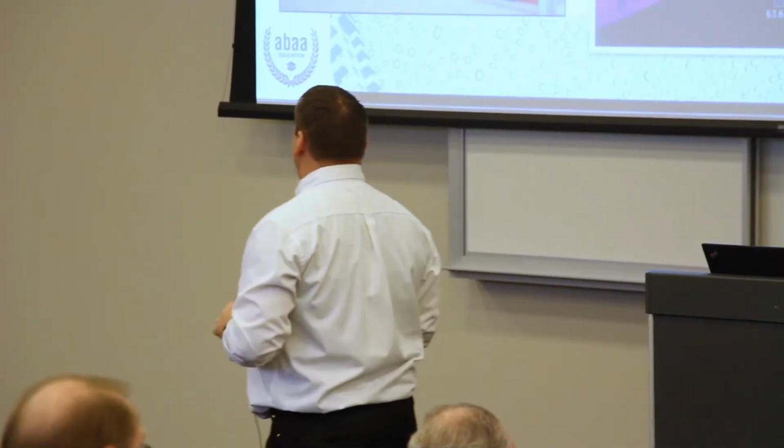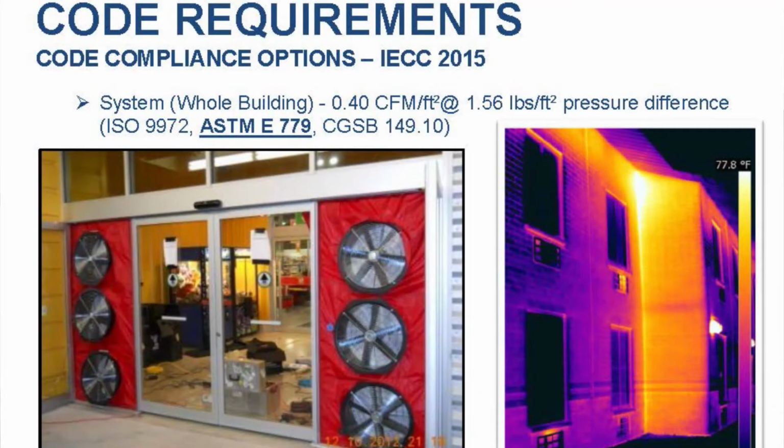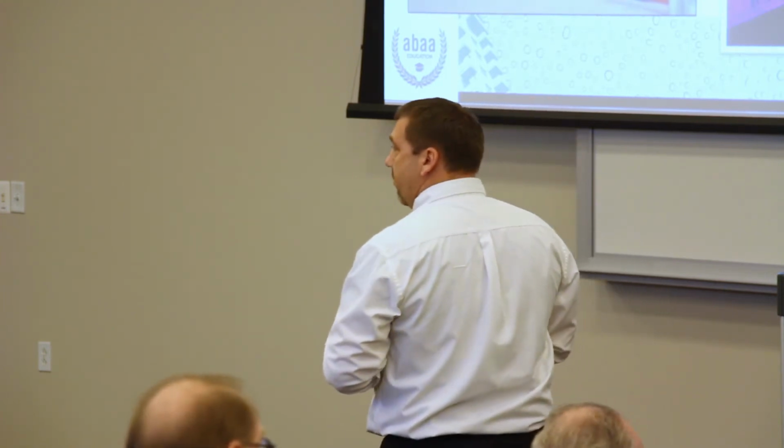We're going to talk about, again, whole building air tightness testing. These are getting easier and easier to run. They're using these small little fans they can place all over a larger building. They're doing multi-story buildings all the time now. Those fans get tied together, either Bluetooth or wireless or Cat5 to a computer, and my understanding basically is they hit a button, the test runs, and you're done. There's more than that, right? Setting up the building properly is the key. But this test, just so you guys understand, is coming. It's going to be in the code before you know it. Yes, sir?